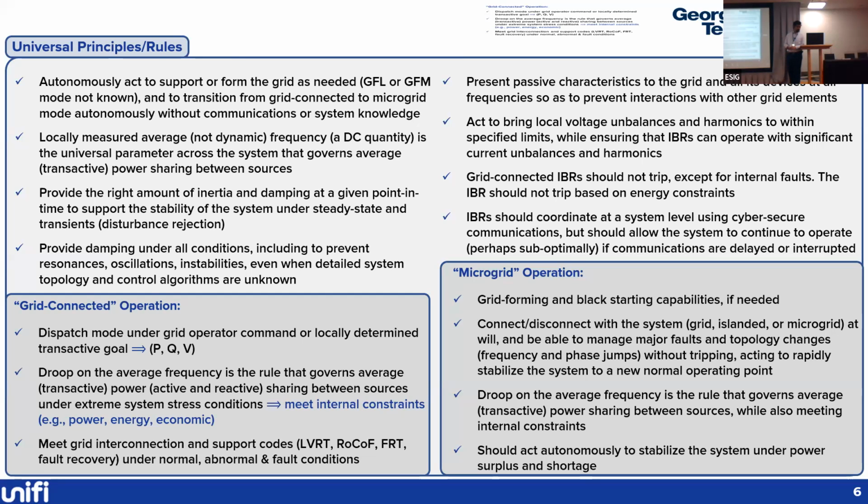We spoke about droop, we spoke about fault ride-through and low voltage requirements. One of the things about the microgrid operation that we wanted to look at is specifically black start capability. Now, we may not require it for all grid forming inverters in the system, but we do want to start bringing in black start capability so that if the microgrid is islanded from the network and there is a reason for it to go down, then it has the capability to be restarted and resynced back to the network.